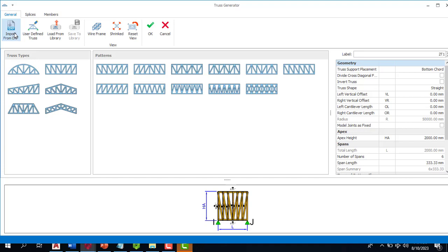So I'm going to be showing you how to import a steel truss. Probably the architect has already given you the cross section of the warehouse or a church or whatever you are designing for. From that cross section given to you by the architect, you can just use it as it is. All you need to do is import that cross section into your Protastructure and use it,